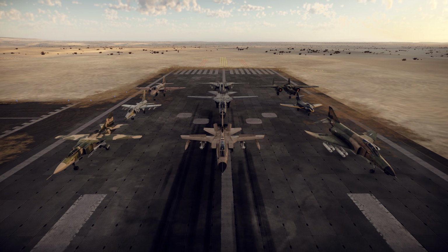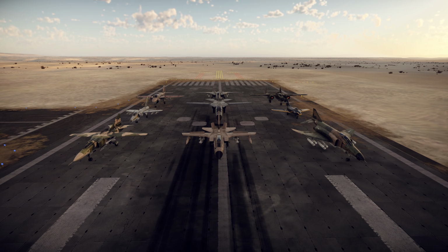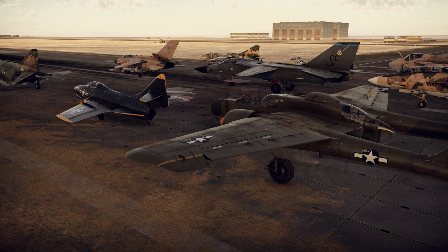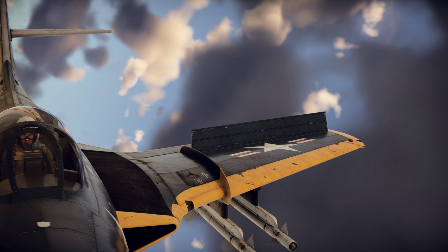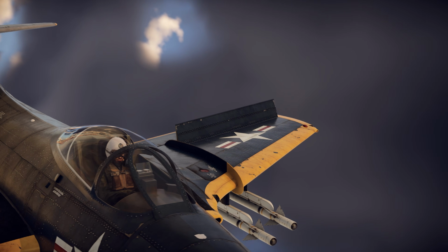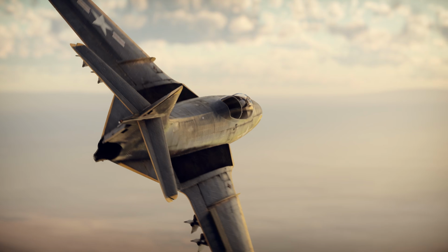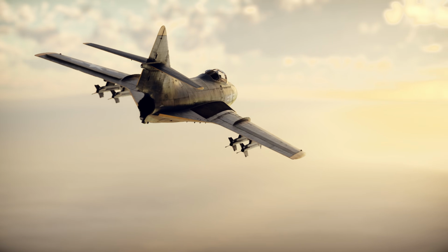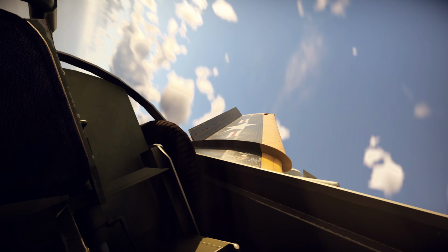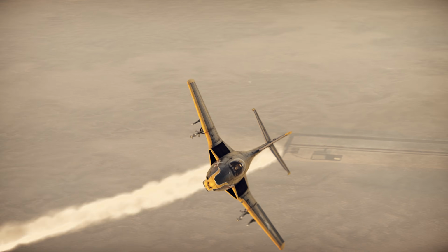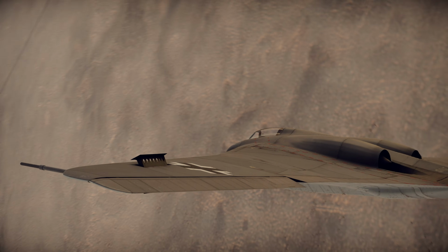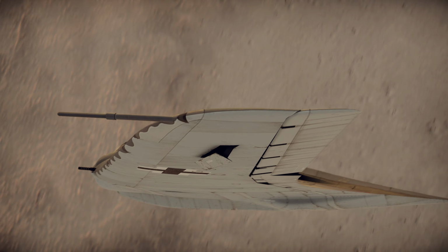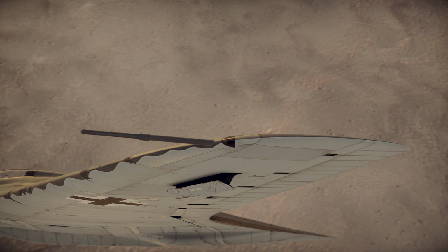Now, let's move on to some less common control surfaces. First, we have spoilers. Not the kind from movies, don't worry. In aviation, spoilers are usually installed on the upper surface of the wing to supplement or replace ailerons. They only deploy on one side, decreasing the lift on half of the wing, causing the aircraft to roll. On flying wing designs, like the German Horten, they are also used for yaw control.